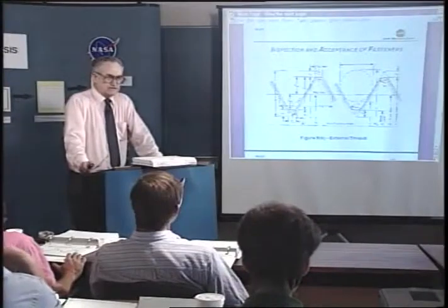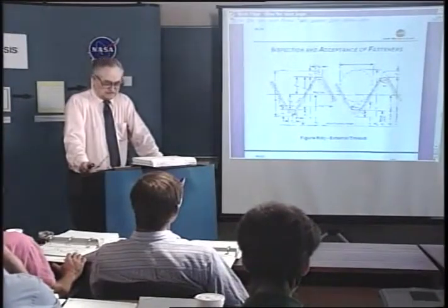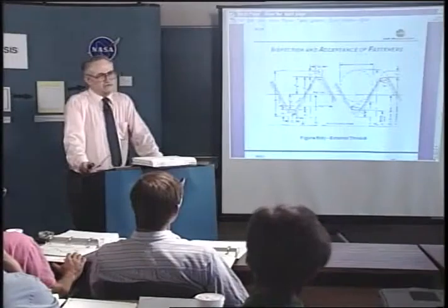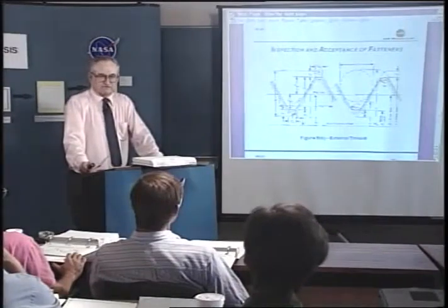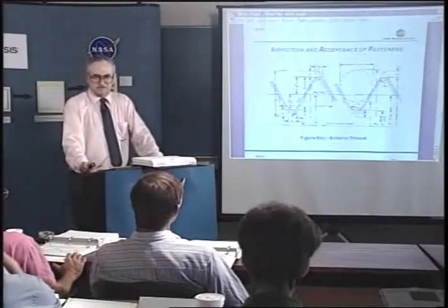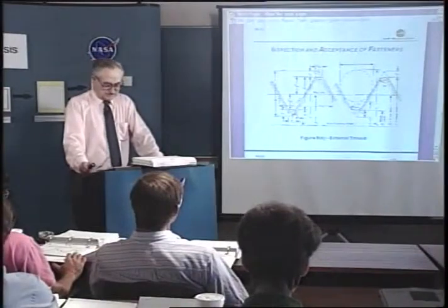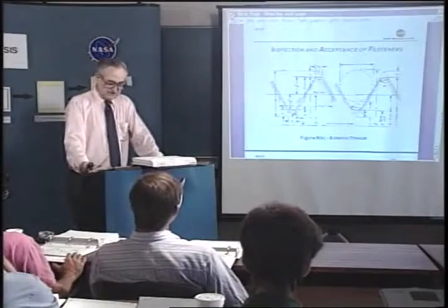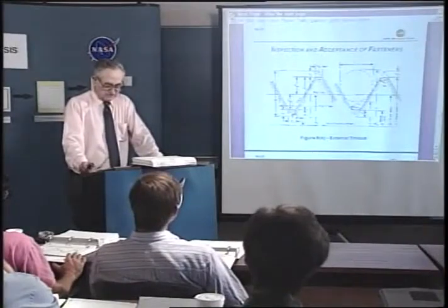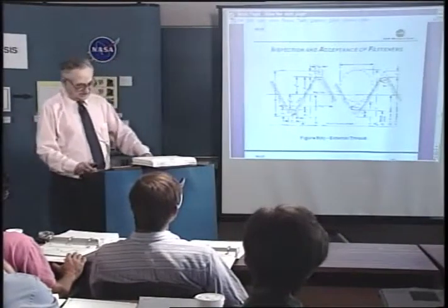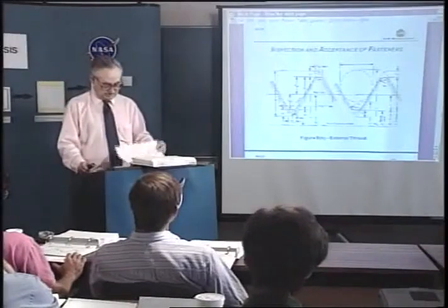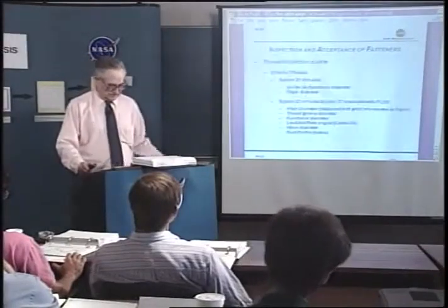There's a method called the 3-pin method where they put the pins, 2 on one side, 1 on the other side, put flat plates across, measure it, then you go to a table, and you can find out from this table, based on the size thread you're using and the diameter of these pins, an accurate reading of the pitch diameter of the thread.